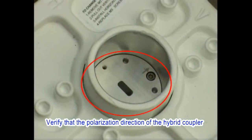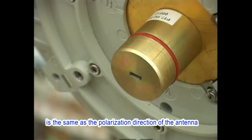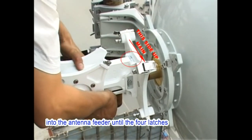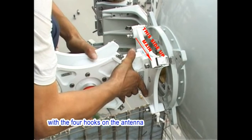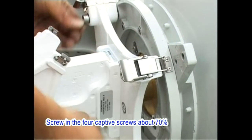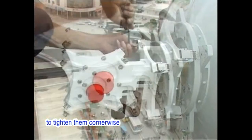Verify that the polarization direction of the hybrid coupler is the same as the polarization direction of the antenna. Slowly feed the antenna interface of the hybrid coupler into the antenna feeder until the 4 latches on the hybrid coupler engage with the 4 hooks on the antenna. Close the 4 latches cornerwise. Screw in the 4 captive screws about 70% on the hybrid coupler and use the hex key wrench to tighten them cornerwise.